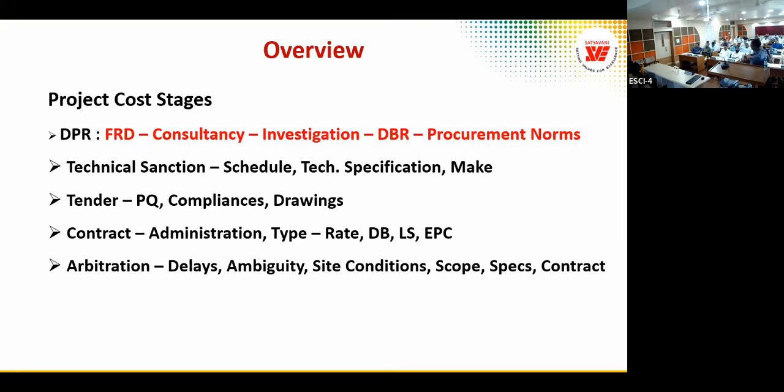Next is the drawings. The drawings that we provide in the tender have to be the same as the DPR. We should not allow "good for construction", people say. Good for construction should only be a stamp and there should not be any modification in the drawing. There should not be addition of any details in GFC.